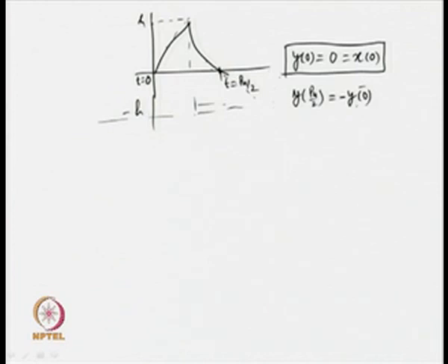What I mean to say by that is that whatever output you get at any instant of time, suppose t equal to beta seconds, definitely you will get minus of that output at time t equal to pi by 2 plus beta. So, output y at time beta is equal to minus of output at time pi by 2 plus beta. Thus we get a typical waveform, which has definitely got half wave symmetricity. I shall make use of these conditions of limit cycle to further explore the way we can use the earlier expressions and get simpler analytical expressions.